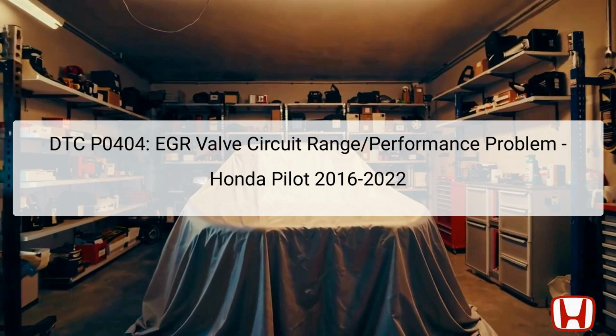The DTC P0404 indicates an EGR, exhaust gas recirculation, valve circuit range/performance problem in a Honda Pilot from the model years 2016 to 2022. This code is generated when the engine control module, ECM, detects that the EGR valve isn't operating within the expected parameters.